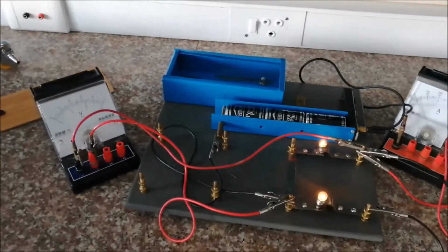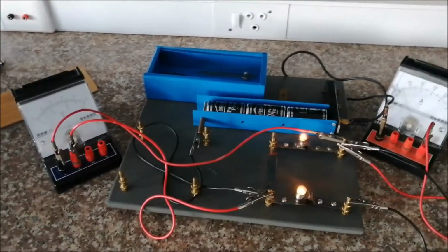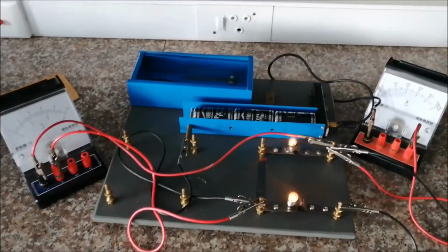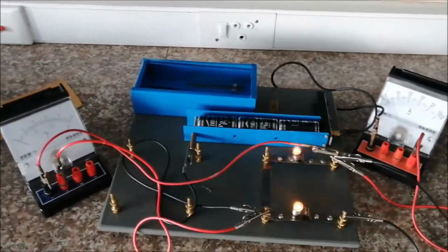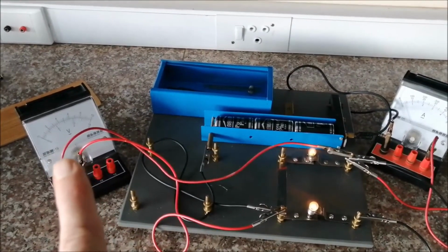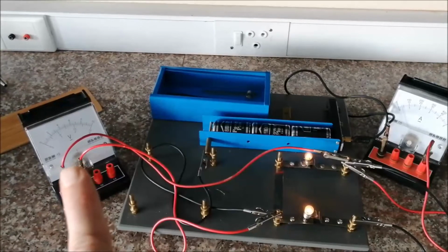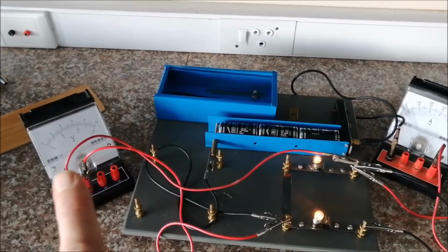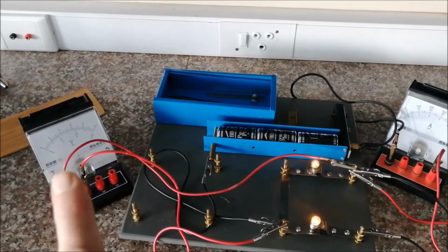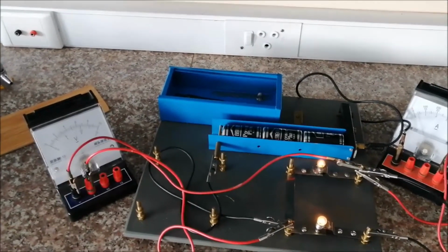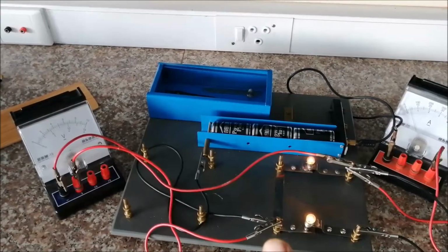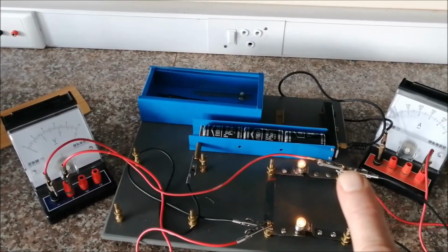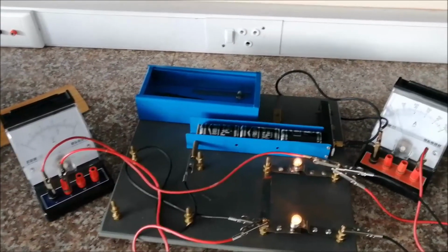elements of it. So we can use the various elements of a circuit to affect the current and the potential difference that is flowing around a circuit. Remember that you attach a voltmeter always in parallel, and that a voltmeter has very high resistance and does not actually form part of the circuit. It just measures the potential difference between 2 points on the circuit. So in this case, we are measuring the potential difference between this point and that point, because that's where the terminals of the voltmeter are connected.